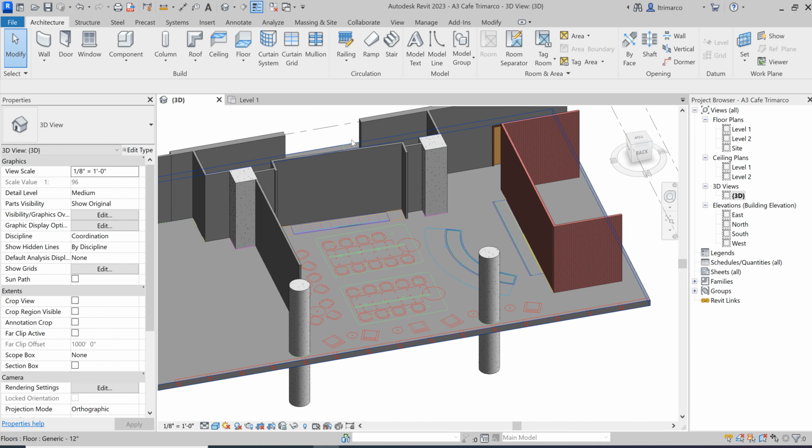With a cabinet like this, you can multiple copy pretty quickly. It's only 36 inches wide, but I can select my copy command, I have constraints on, I have multiple on, and I can just move into an endpoint. Again, object snaps automatically are on in Revit. You don't have to turn anything on or change anything. It's just part of the package, part of the template, I should say. I'm selecting endpoint to endpoint to endpoint, and it's just creating this long base.